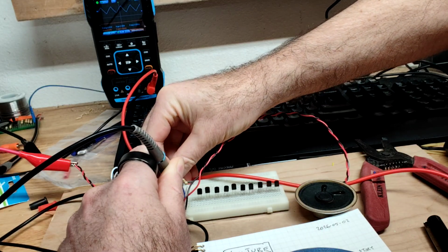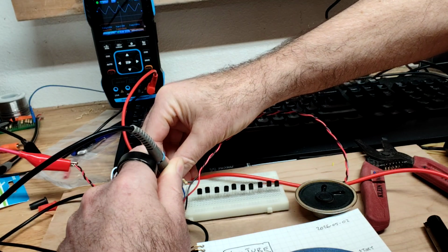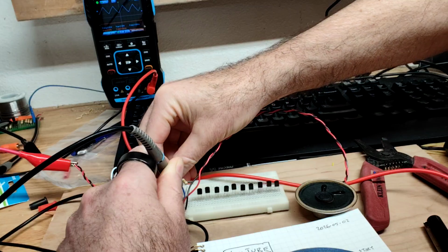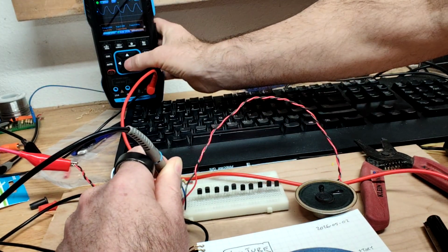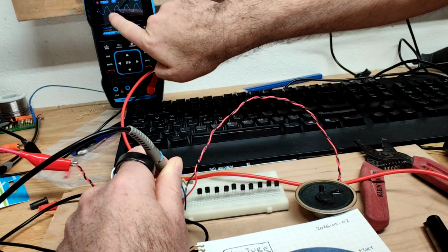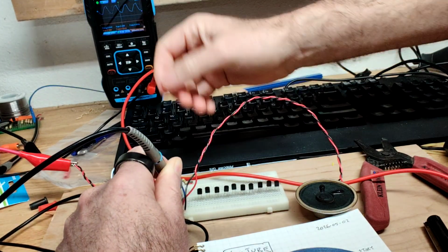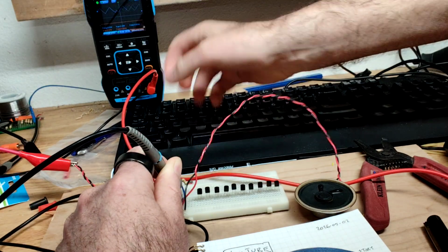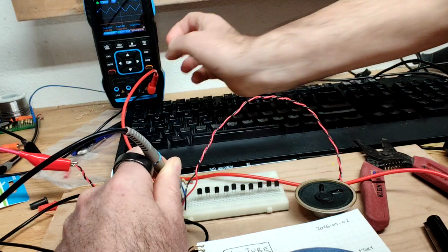But you see, as I bring it up higher, I hope you can see that. You see how the top of that peak is getting rounded off a bit? It has a little inflection point. Let's see if I can pause it here. There we go. You see how it comes up and then goes over. And if I bring it down a little bit, it's that perfect sawtooth wave.